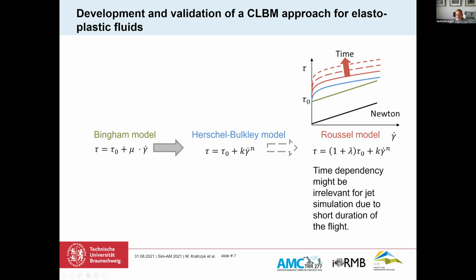Could also consider to implement the Russell model, but we believe presently that the time dependency in the Russell model might not be too relevant because we're looking at the jet and this is a short time scale. And so we don't think that this droplet dynamics will be very much dependent on the time dependence in the rheology. So we try to stick with the Herschel-Bulkley model.